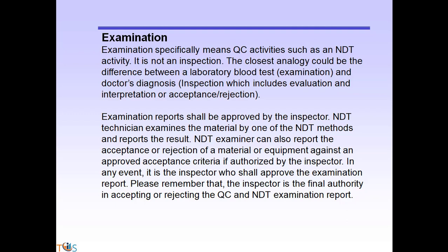Examination. Examination means QC activities such as NDT. It's not an inspection. The closest analogy would be the difference between a laboratory blood test examination and a doctor's diagnosis. Inspection includes evaluation and interpretation or acceptance/rejection. Examination reports shall be approved by the inspector.